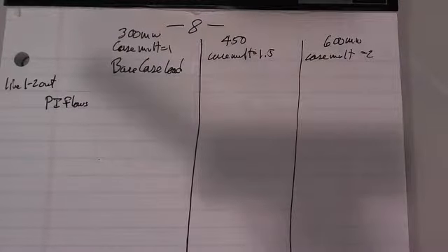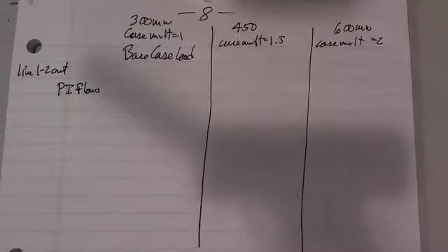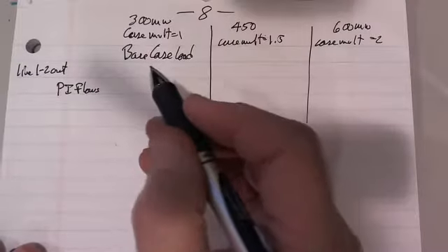You look back in the book. There's also a PI, a performance index for voltage. It's a little more complex, but it simply involves subtracting the voltage from either its upper or lower value and raising it to a large power.